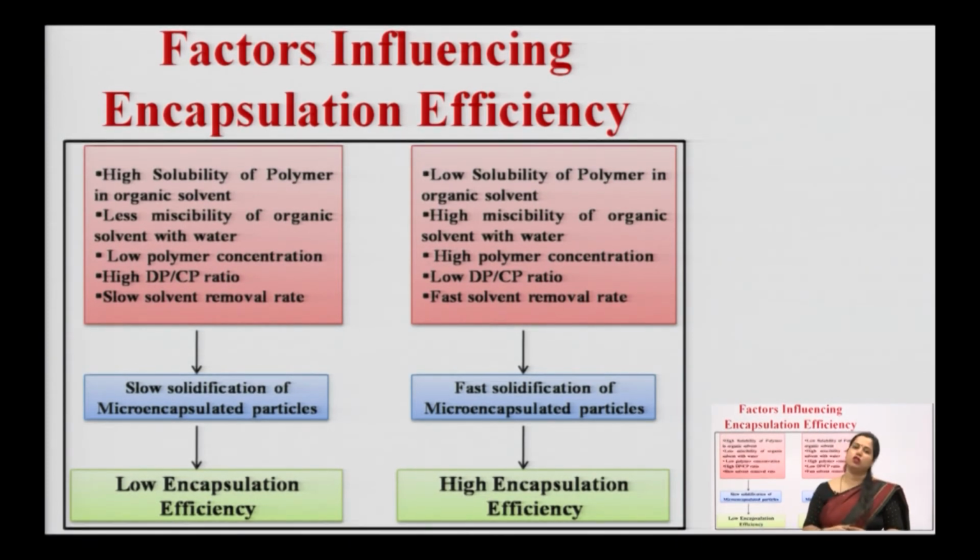in low encapsulation efficiency. Whereas, the vice versa is low solubility of polymer in organic solvent, high miscibility of organic solvent with water, high polymer concentration, low DP-CP ratio, fast solvent removal rate will lead to fast solidification of microencapsulated particles, and finally, it leads to high encapsulation efficiency.